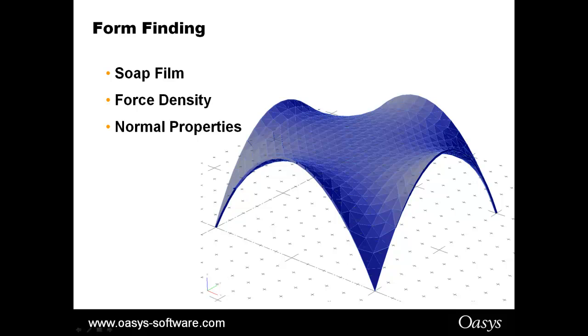It's different to most analysis methods because it doesn't produce forces and reactions as the end results. It produces a change to the model itself plus pre-stress forces. This new geometry and the pre-stress forces you then take on to further analysis for the static cases.